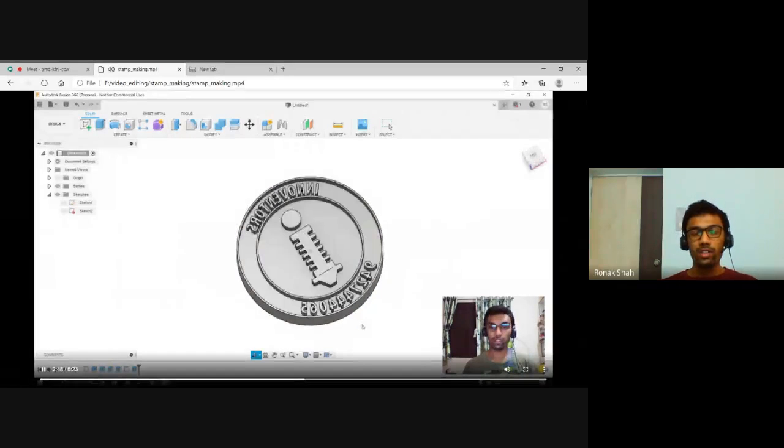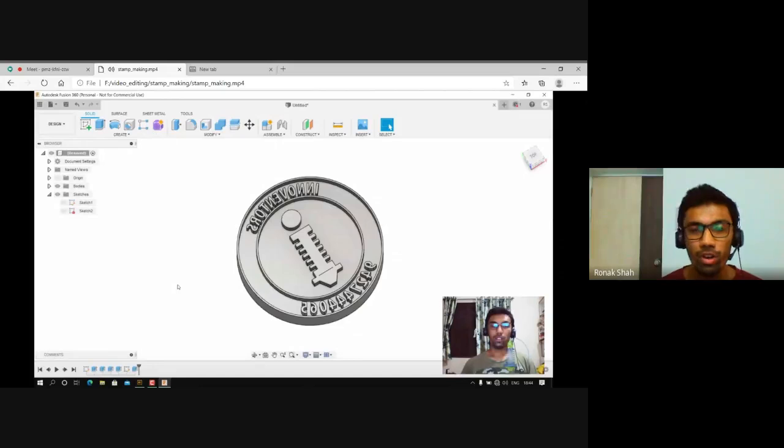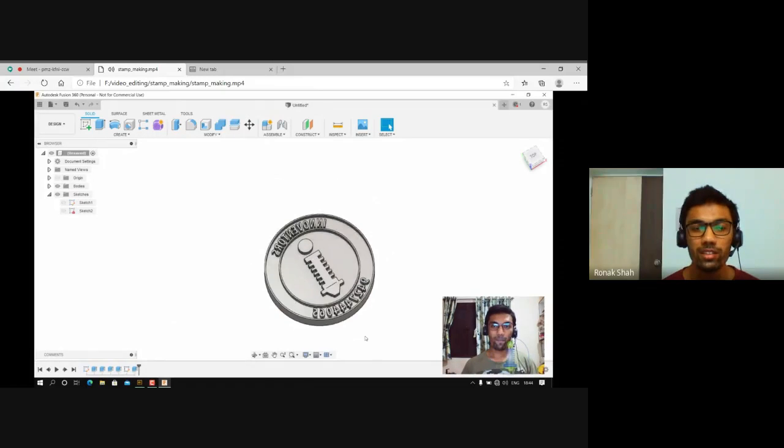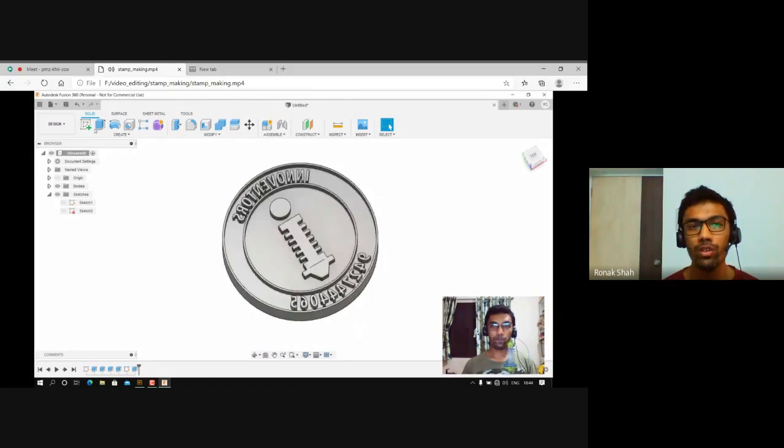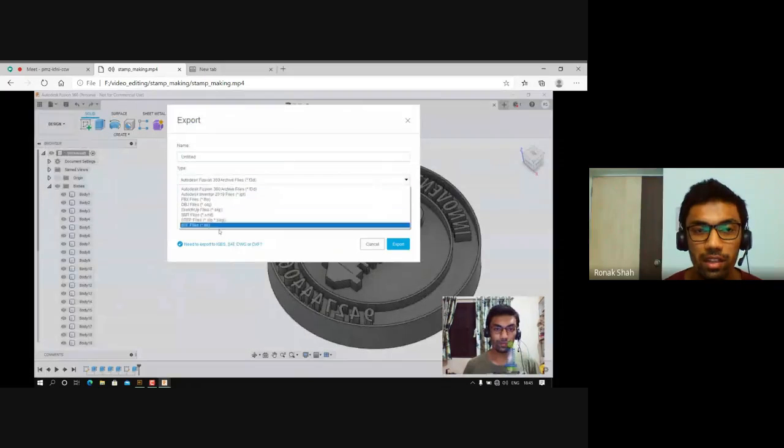So now your 3D model is ready. For printing this, as I said earlier, we need to export it in a neutral format. So we are exporting it in an STL format.